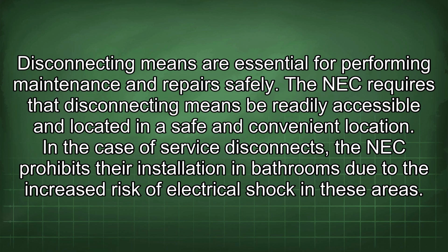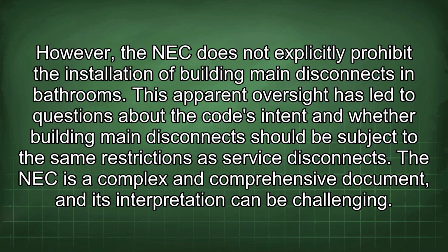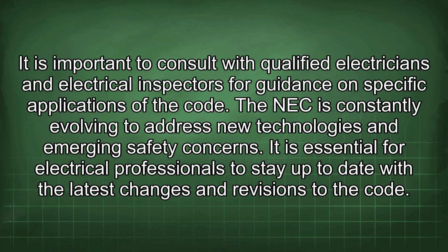shock in these areas. However, the NEC does not explicitly prohibit the installation of building main disconnects in bathrooms. This apparent oversight has led to questions about the code's intent and whether building main disconnects should be subject to the same restrictions as service disconnects. The NEC is a complex and comprehensive document, and its interpretation can be challenging. It is important to consult with qualified electricians and electrical inspectors for guidance on specific applications of the code.